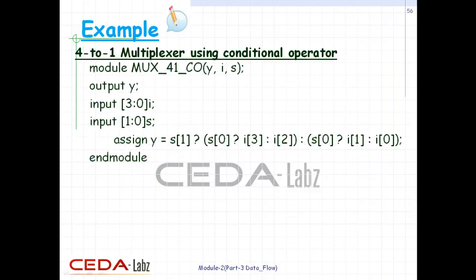There is a more concise way to specify the 4:1 multiplexer. In the conditional operator section, we described how a conditional statement corresponds to a multiplexer operation. Convince yourself that this description correctly models a multiplexer by analyzing it again and again. In the simulation of the multiplexer, the gate-level module can be substituted with the dataflow multiplexer modules described above. The stimulus module will not change. The simulation results will be identical. By encapsulating functionality inside the module, we can replace the gate-level module with a dataflow module without affecting the other modules in the simulation. This is a very powerful feature of Verilog.